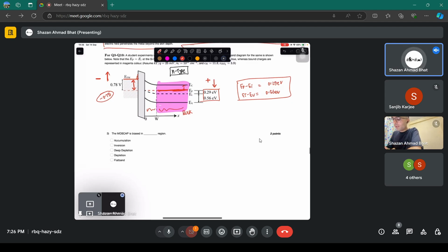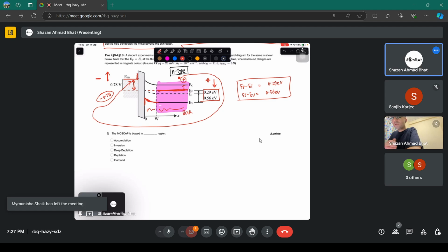The next point, now it is N-type. You have connected negative here. You have connected positive here. What has it done? It has created a bending like this. It is as if the N-type was having positive ions and excess electrons. Those excess electrons have been taken away, deposited at the metallic side. And what it has done, it has made this system devoid of electrons.